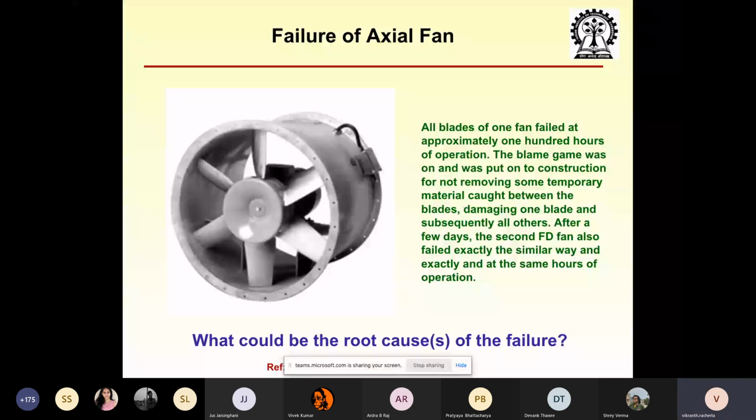What does resonance do to the loading on the blades? What happens in resonance? The amplitude of vibration goes up successively. Amplitude of vibration increases tremendously. Particularly if it is an all metal structure, it doesn't have much damping, and the amplitude of vibration will be much higher, maybe 5 times, 10 times that of the normal loading. So what is the harm? Let it vibrate, let the amplitude be high. What is the problem? But the strains will be too much if the amplitude goes unchecked.